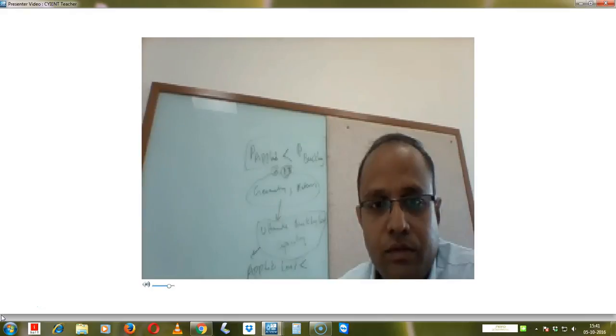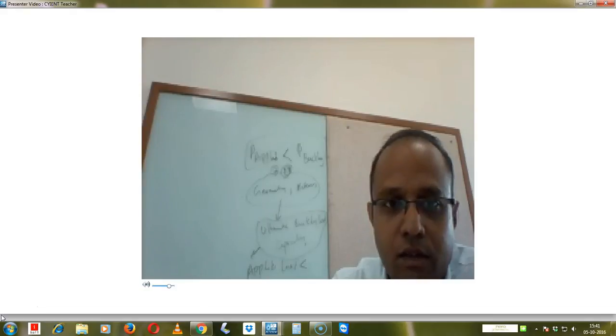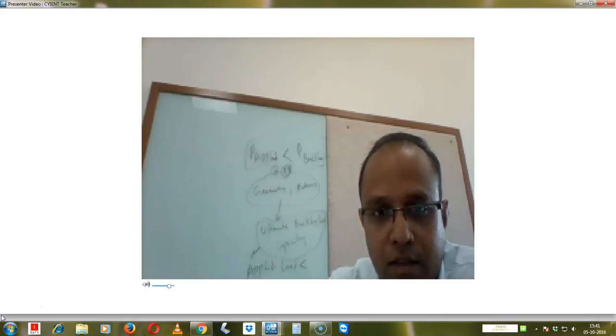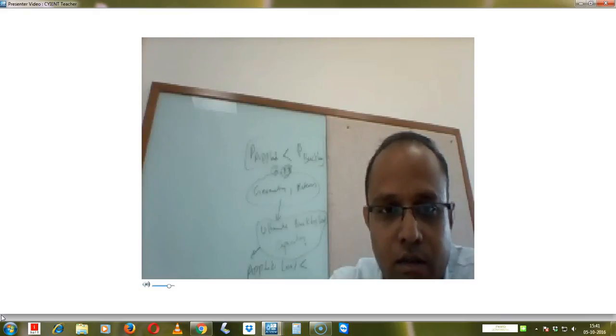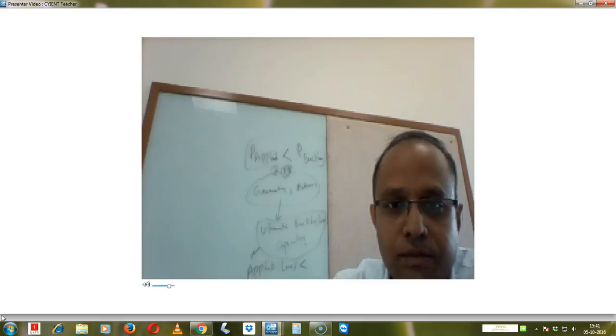So if you see here, we might have studied buckling loads in our strength of materials. So there are various conditions here: one end fixed, pinned, fixed, hinged, all those things. There are 5 conditions over here. All are given by Euler buckling. So Euler buckling is given by this equation, K into pi square EI by L square, where K is given for each condition. For this condition, condition 1 will give maximum buckling load. So it can withstand maximum buckling loads.